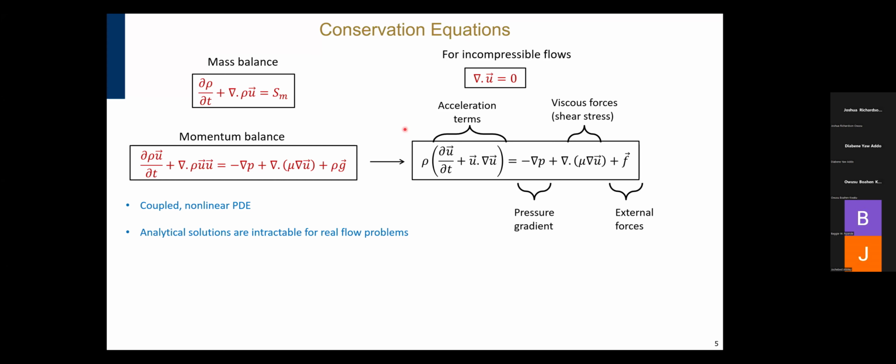If your crystallization or nucleation step is much faster than your mixing times, then you definitely have to consider mixing and try to improve your mixing. But if it is the other way around, where your mixing is relatively fast compared to your nucleation, then you can get away with it. So those are some of the considerations out there.